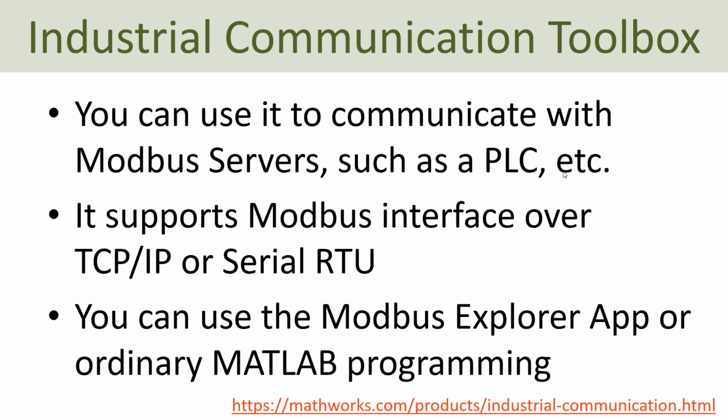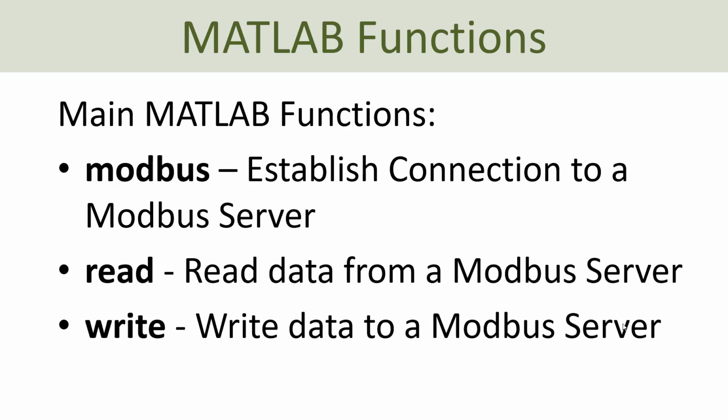We will use this Modbus demo software, so we will create scripts in MATLAB and then communicate with the Modbus demo server, which I had previously shown and demonstrated. And the Modbus support in the Industrial Communication Toolbox supports both TCP/IP and serial RTU. And you can also use this Modbus Explorer application, which is a graphical user interface, in order to communicate with a Modbus server. But let's start to see how we can use Modbus in ordinary MATLAB code.